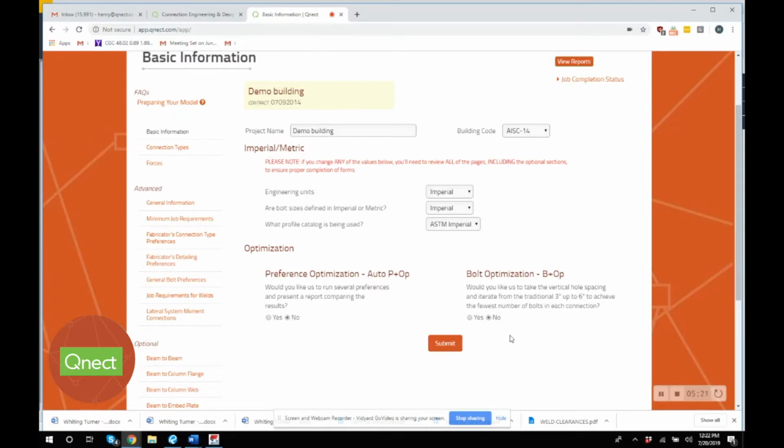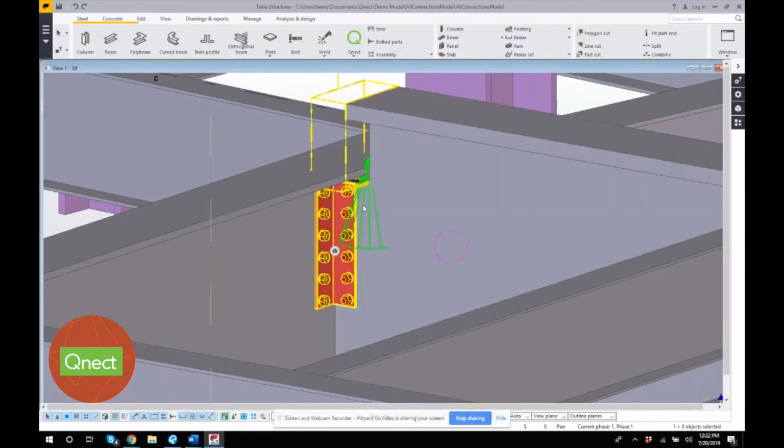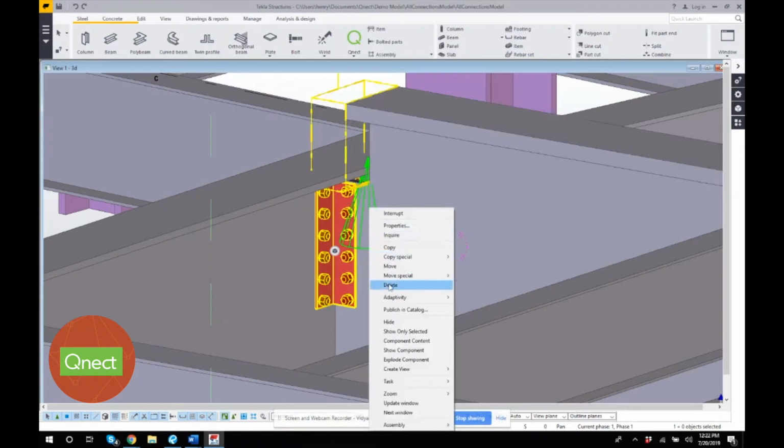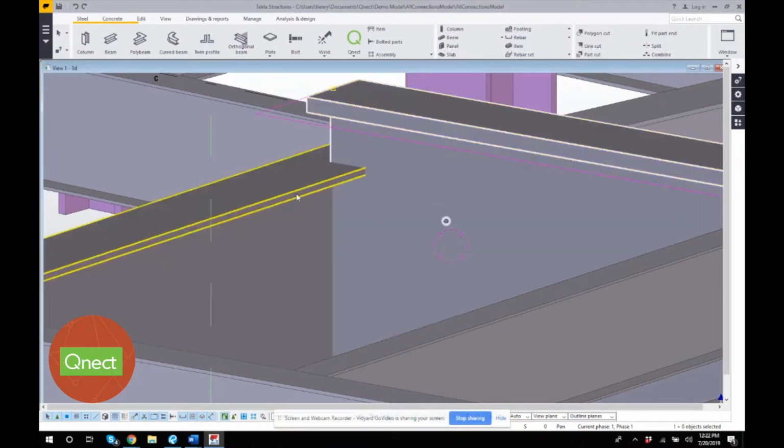Full engineering. We'll compare the results and then select the vertical spacing with the fewest number of bolts. So we just have to say yes, we activate it, and then we come back to the website and we'll just observe that there's 6 bolts, and we'll delete this connection. And now we're going to run it for an optimized joint.